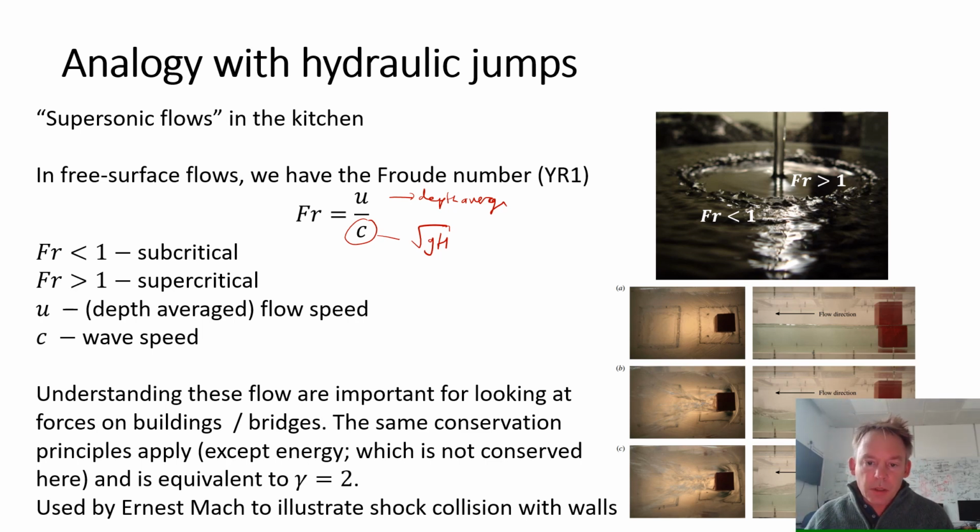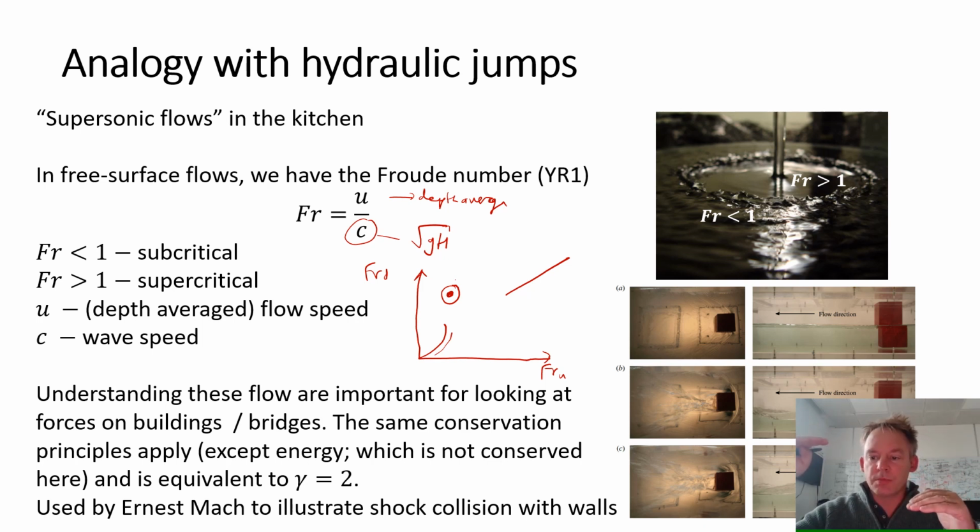And what's interesting, and we've done a lot more work on this, is if we look at the Froude number upstream and the Froude number downstream, the flow jumps into a lock state, and then there's another branch over here. We've done this experimentally and computationally, and this is important. If you have a tsunami past a group of buildings, as the flow speed increases, it jumps to this critical flow state, which is characterized, as we see down here, by a very large difference in water height between one side and another of the building, and elicits a very large resistance force, which causes it to be swept away. And this is essentially a jump.